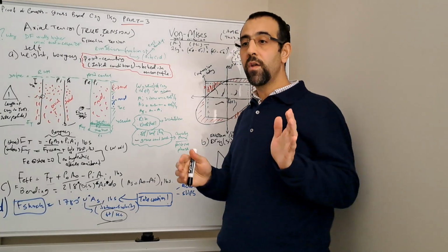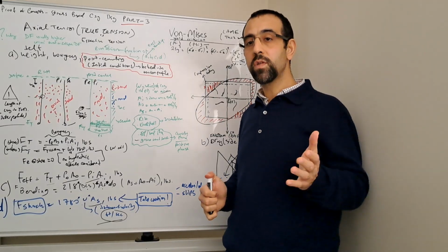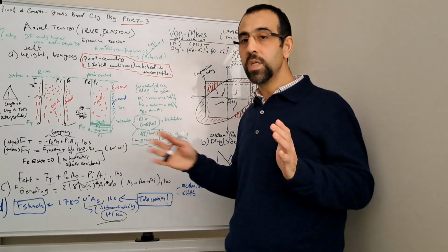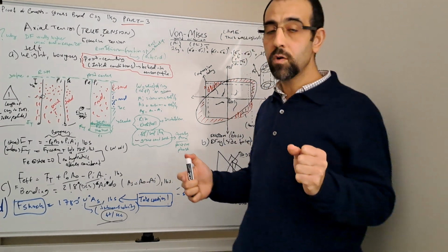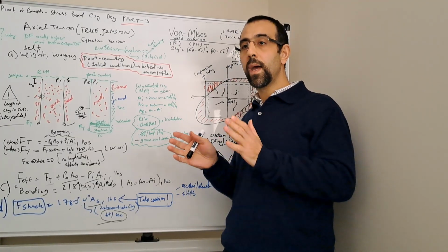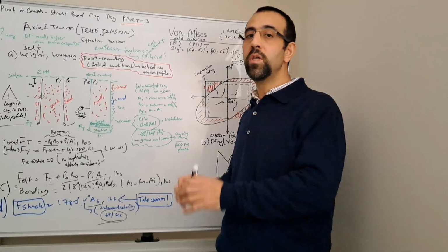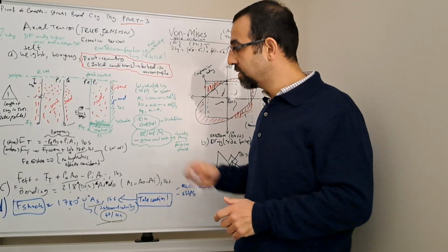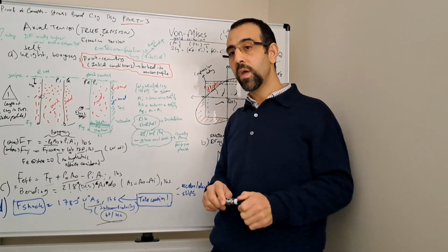That's day one of your stress profile. That's locked in, and then any other load cases in the life of the well, during the completion or in the subsequent hole sections, let's say a gas kick or a full evacuation, whichever you call it, will have an associated ballooning. That ballooning will be superimposed, or added, into this axial tension profile, and that's how you come up with design factor ratings of the load cases in terms of axial tension.